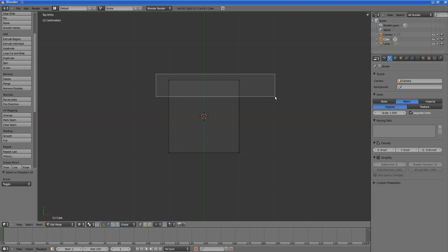these vertices and delete them, and then border select these vertices. Now I want to move these four vertices in the negative y direction. I can do it using the cursor pivot mode, and my cursor is at the world origin.